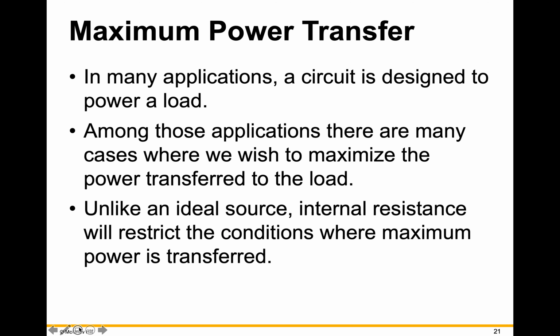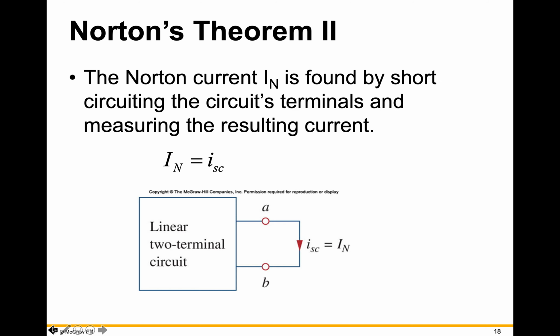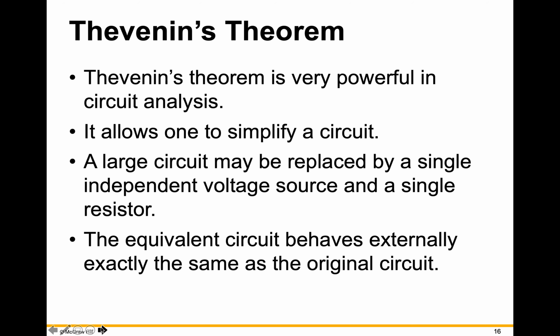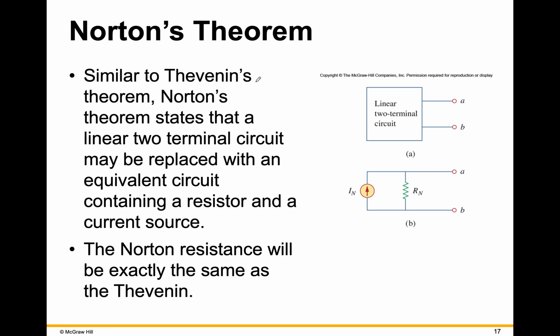I think this reaches the end of what I want to cover in this video. But I do want to point out one thing. Thevenin and Norton is dependent on where the terminals are located. So suppose, for example, you had a couple of other terminals that came out of here, maybe C and D. The Thevenin or Norton equivalent circuit is not the same for A and B as it is for C and D, unless it's just some kind of fluke of geometry.